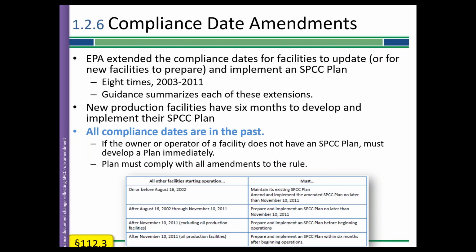Now, recognize on the setup for this operation, you may be asked to press the piping, and when I mean press, test the piping or the tank system with fuel in it. You should have the plan in place when you're doing that. It's not just when you say, hey, we're open. It's whenever you put oil in the tank.